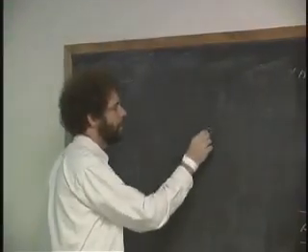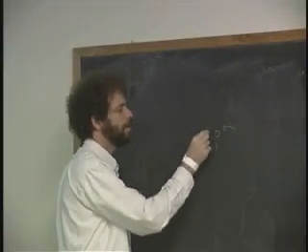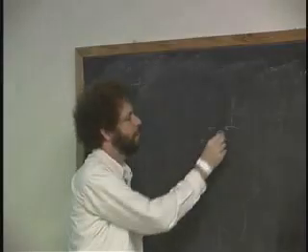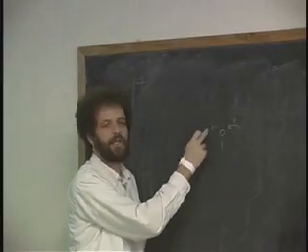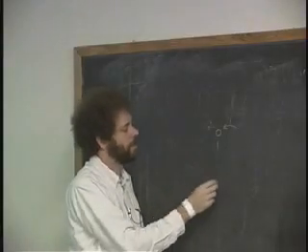Well, when's that going to be true? I'm going to want to propagate the carry when? If it's 0 and 1 and a carry comes in, should I propagate the carry out? Yes. 1 comes in and a 0 and 1, should I propagate? 1 plus 1 is 0. Yeah, okay, so that's one case.